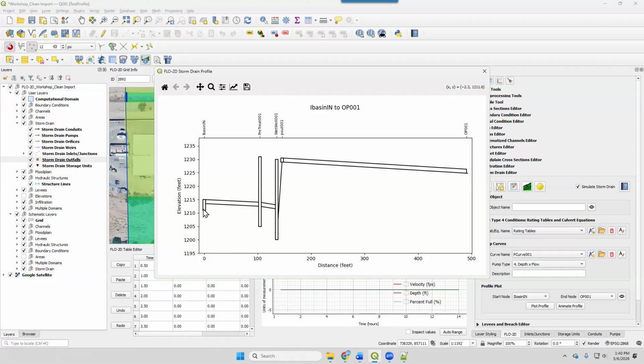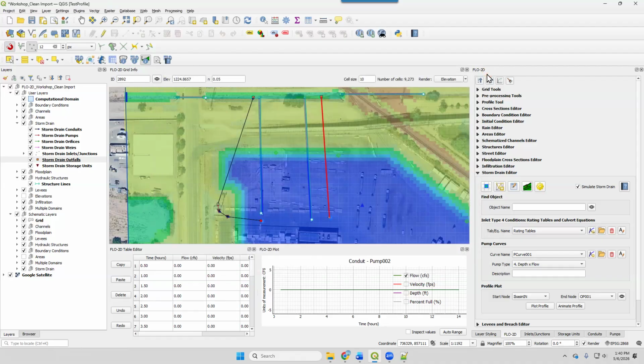So our invert elevation is 1211, rim elevation 1215, then our conduit, and then that would be that offset per the standards of the treatment tank, and then the offset per the standards of the, just got to get that water to that gravity feed, get that to the wet well. And then the pumps, of course, are inside the wet well, so it pumps it from that up to the outlet works, and then the outlet works is just a conduit taking it down to the outfall. Now, let's see, what else should we do? I guess that's it. That's the profile.